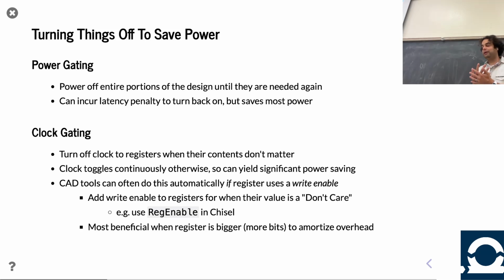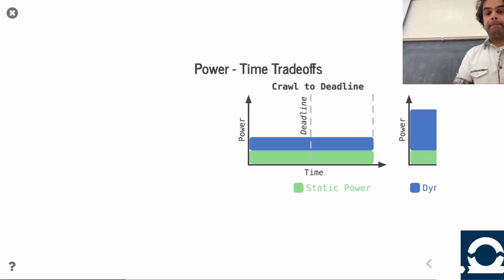And so that don't care propagation is somehow two different concepts that are mapped to the same construct, right? Chisel has worked really hard to eliminate both, but really they care more about eliminating the simulation don't care. So the simulation don't care doesn't really exist in Chisel. All values are initialized. There's no notion of undefined in simulation. They're randomly initialized. The logic behavior don't care to allow tools to optimize does exist under constrained circumstances. This is one of them. Here I'm saying use RegEnable. Technically, if you have a regular Reg and you have when statements, you can get the same behavior, right? Cool. Good questions. Okay.